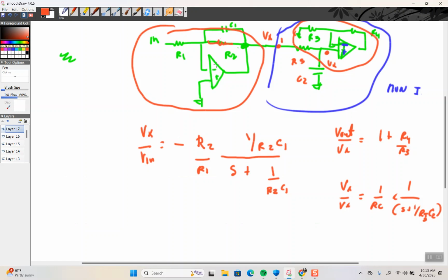But at low frequencies, this capacitor becomes infinite, and then it just becomes an inverting amplifier, so you get minus R2 over R1, right? And then I remembered, oh, that's what it is. Okay, because we're in a rush, you multiply all of these together. And then, we're out of time, so there's derive it, and then there's do the Bode plot, things like that. All righty, have a good day.